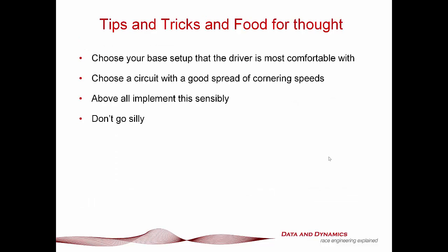So to wrap this up, I'm going to give you some food for thought. Okay, first things first, you choose your base setup that the driver is most comfortable with. Not necessarily what's the quickest, but what they are most comfortable with. Remember, we are tuning for drivability here, ladies and gentlemen. We're not tuning for grip. We choose a circuit with a good spread of cornering speeds. I cannot understate that point enough.